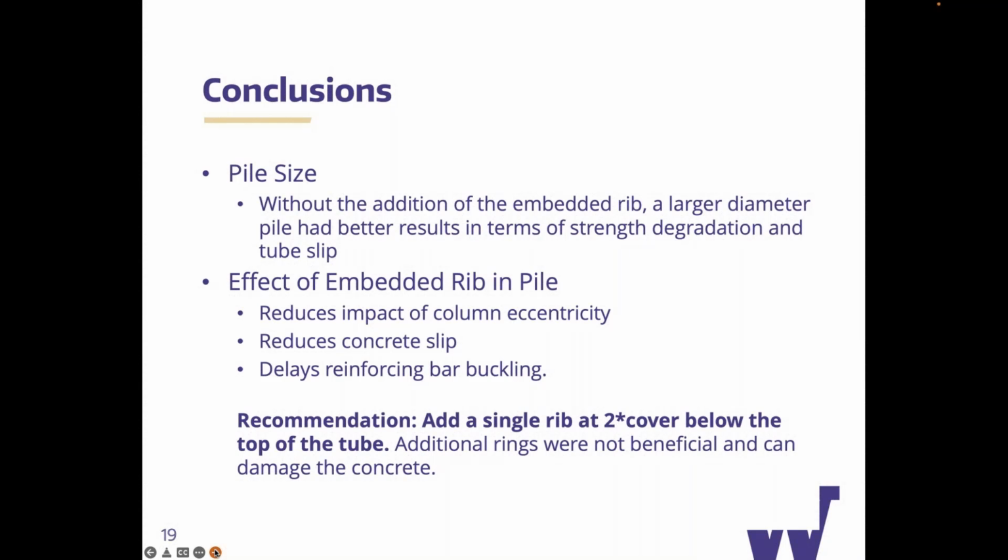But I do also think, although we haven't studied this experimentally, it's important to think about what that concrete area or thickness is relative to the bar diameter as well, since we know that a larger bar is going to need more concrete to allow the struts to develop from those deformations.